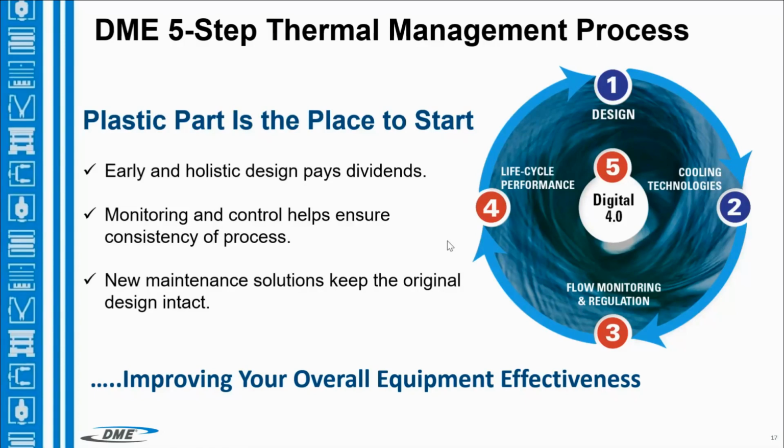You're going to find it happens a lot more than what we want to admit. But if you had a simple monitoring system on there that was tied into your molding machine, it would alert you before you made tremendous amounts of scrap and help you address the problem quickly versus being reactive.